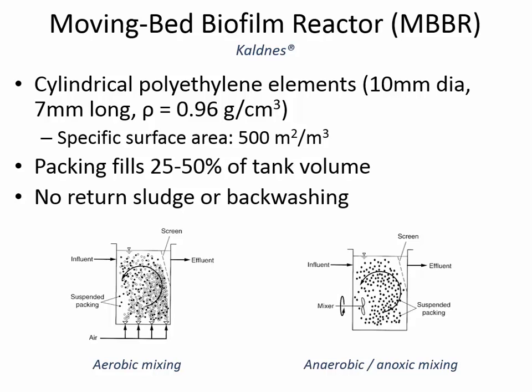That's where the solids are, that the growth of the substrate occurs inside of the aeration basin, and there's no return sludge, no backwashing. Eventually the solids are going to be removed, but it comes out of the effluent, and so there's a clarifier downstream of it. There still is a clarifier. It's just that you don't have to put the sludge solids from the clarifier into the aeration basin.